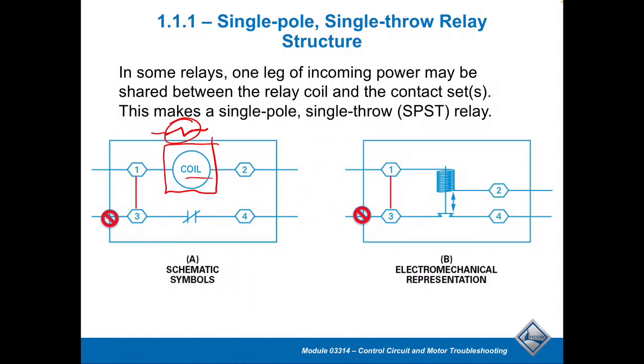And of course, the contacts. This one is showing me a set of contacts that, in this particular case, is identified as, let's say, normally closed in this manner. Now, electrically, what it looks like is, in this particular box or relay, they're identifying the power coming into terminal number 1, and so the coil terminals are 1 to 2, and of course they have a jumper going between 1 and 3.